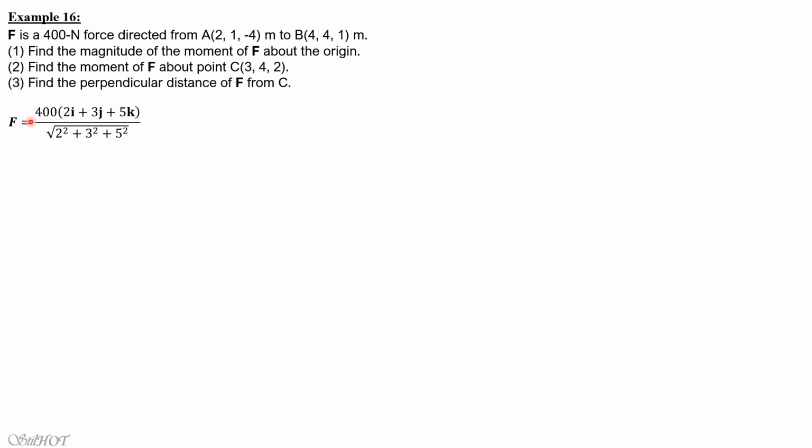Remember, the components of force are magnitude times components of distance divided by distance. So it is equal to 129.78i plus 194.67j plus 324.44k newtons.